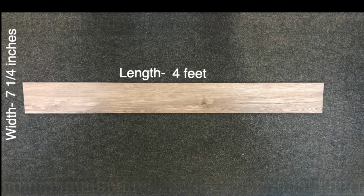Okay, let's have a look at this. If each piece of the vinyl plank material measures 4 feet in length by 7.25 inches in width, we can use the area formula for a rectangle to determine the area covered by one piece. But first, we have to make sure both dimensions are expressed in the same units. Since we calculated the area of the room in square feet, we'll do the same for a single piece of flooring. The length is already in feet, but the width is measured in inches, so we'll have to convert that to feet as well. We'll do that in a separate side calculation.